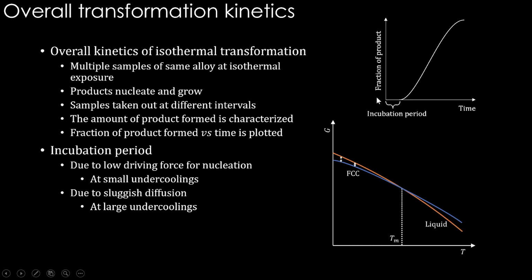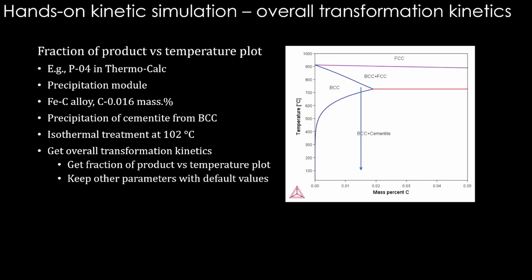So this graph gives you an idea of what the incubation period is at different temperatures and how the transformation happens with respect to time until it is completed. All this information you can get from an overall transformation kinetics graph of this sort. Okay. Let's simulate this taking an example. A plot of fraction of product versus temperature will follow.